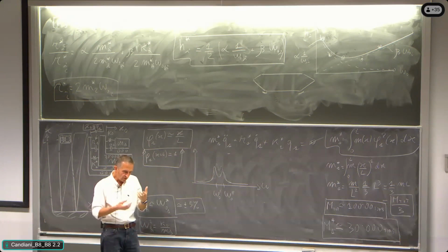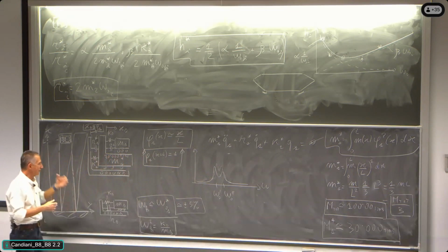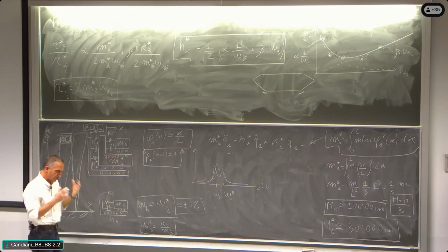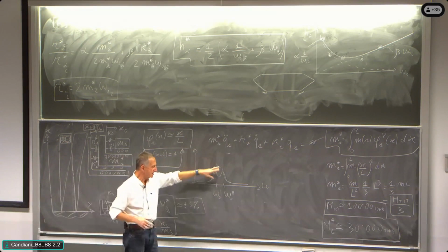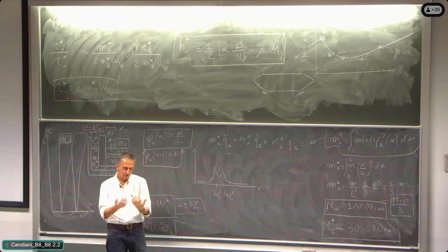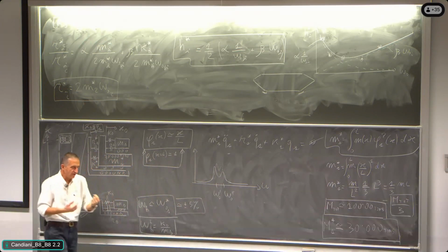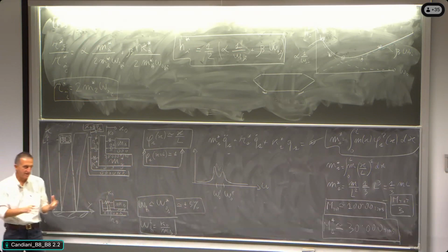So then the point of estimating from this 2-degree of freedom system the effect in terms of non-dimensional damping of this mode that is increased by this damper is a bit tricky. We are not discussing it, all right, but it's possible to discuss. So the discussion of the TMD goes into the discussion of this 2-degree of freedom system that is mixing the modal damping of the mode 1 plus the mode of the TMD with respect to mode 1, and then finally the modal behavior of mode 1 of the structure shows an increase of its non-dimensional damping.